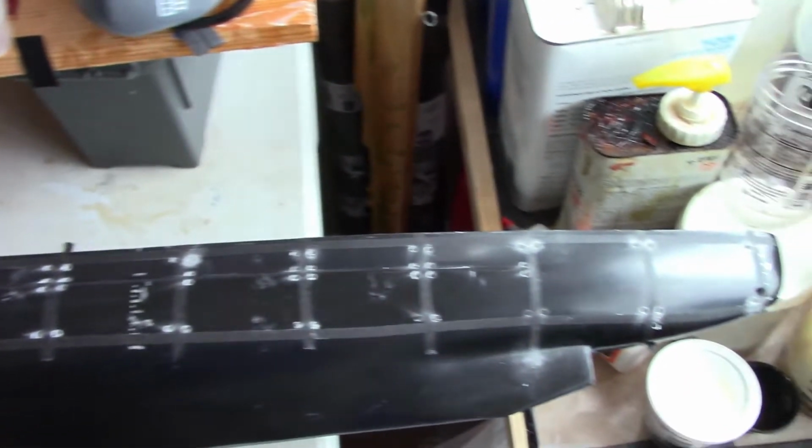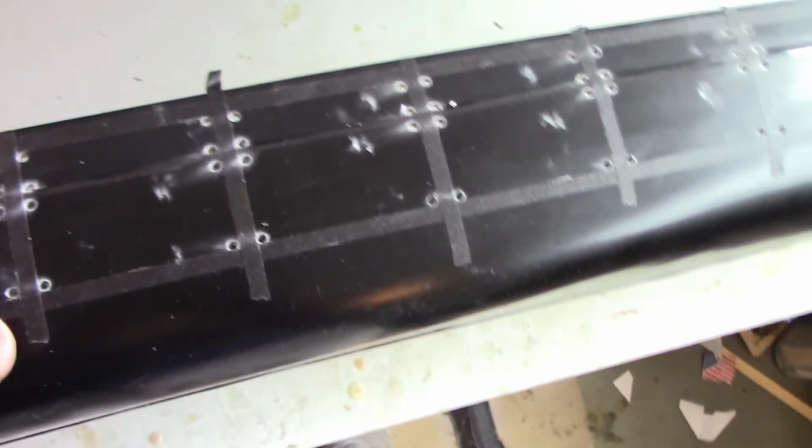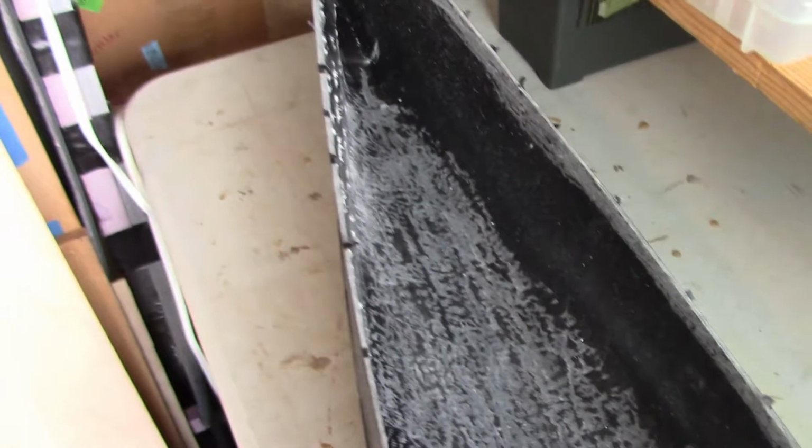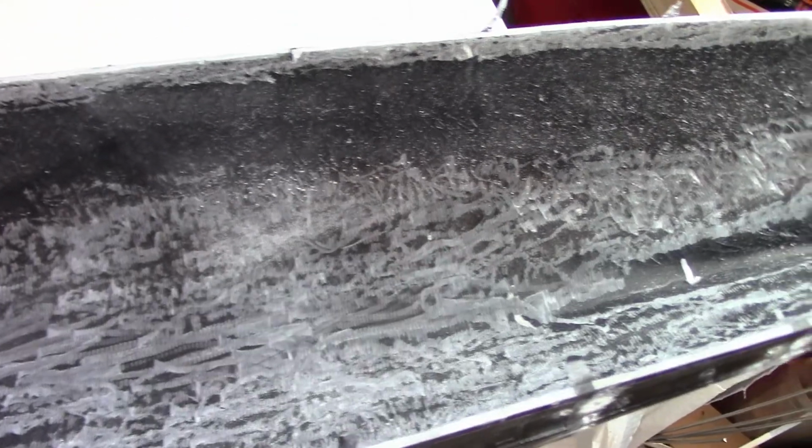All the holes are drilled out on this side. You can see them there. I also finished roughing up the inside, so you can see the contrast there. I'll still probably hit this with some sandpaper to even it out, but the Dremel does a really good job cutting up that outer layer so you hit the fibers to adhere to. Some of the hard to reach places, like where the keel is at the very stern, you'll have to get with sandpaper or a different bit on the Dremel.